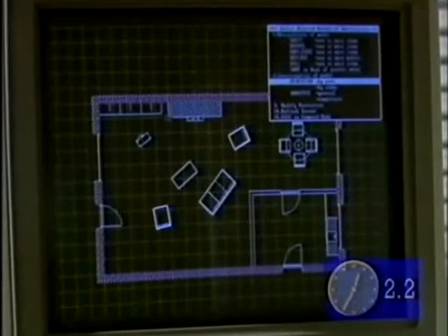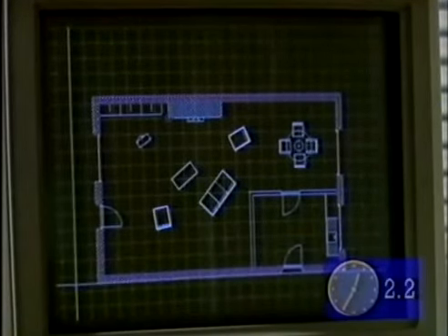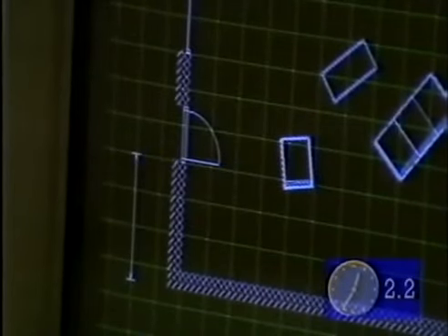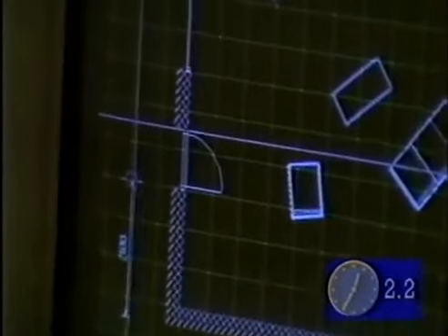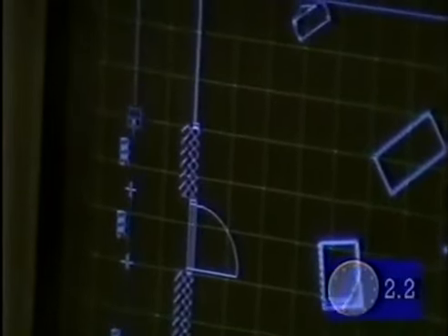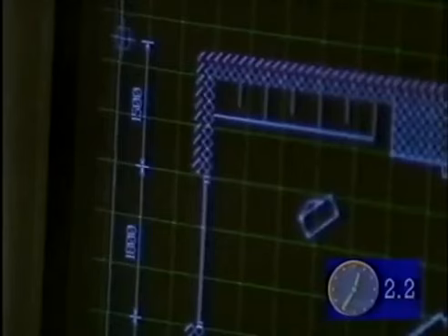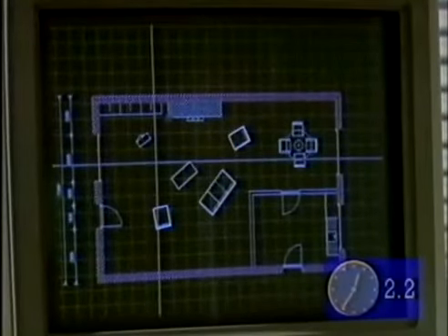So I'm selecting from the screen menu, dimension by puck, and all I need to do now is simply say start dimension, let's say there, end dimension. Right. And it calculates that distance and puts in the text accordingly. Puts the size on. So it is start, end. Yes. Because the description in the machine is to full size, these calculations can be made directly. That's right. And we can do a total run all the way down there. Lovely. And you know that run equals the total run as well.